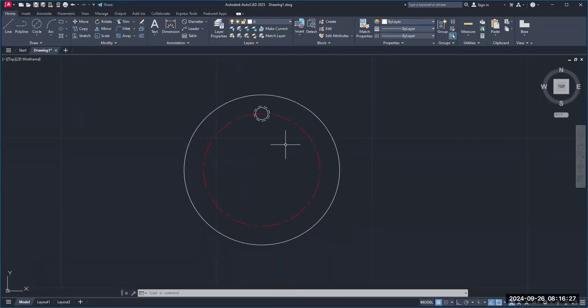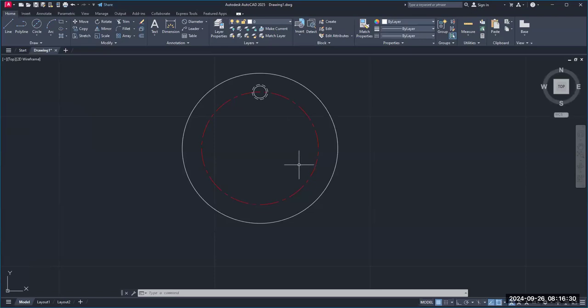Okay. All right. Now we're going to go make the hole at the 3 o'clock position. The hole at the 3 o'clock position is a what type of hole? It's a countersink hole. How do I know that? Because look at the symbol. It looks like a cone shape. How many of y'all have seen a countersink screw before? None of y'all ever seen a countersink? They call them flathead screws. Okay, so it fits into a countersink hole.